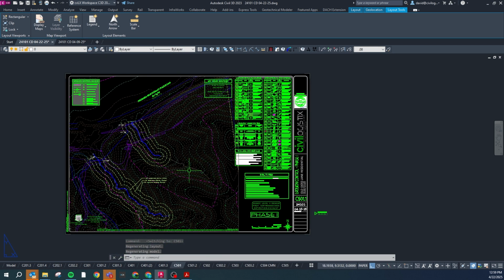So make sure that when you're setting up your sheets, each viewport size or location has its own layer, and then make sure they're all matched so they're the exact same location and exact same scale, and when you flip sheet to sheet, they show up in exactly the same spot. And that's it.